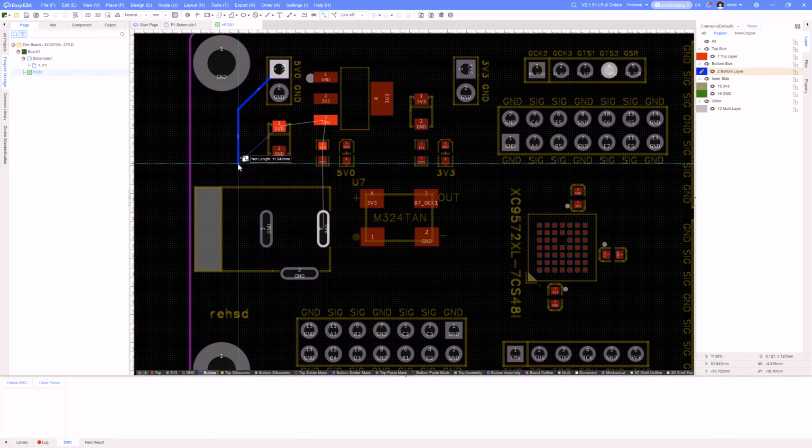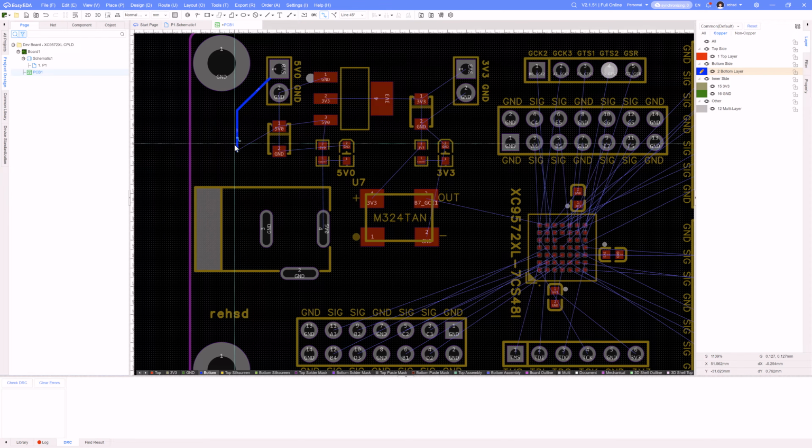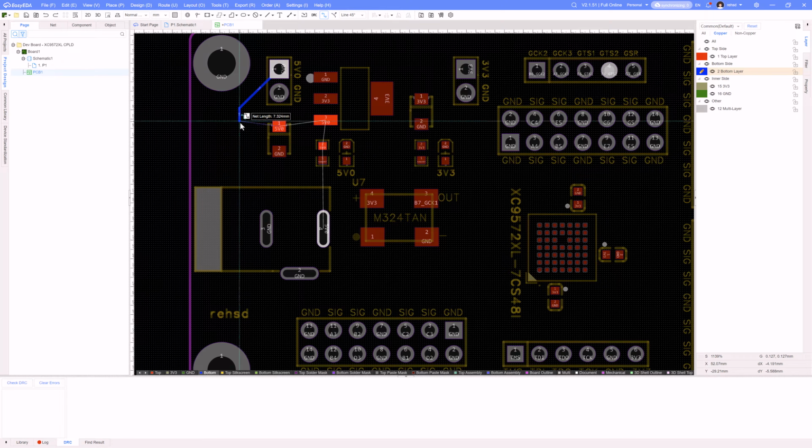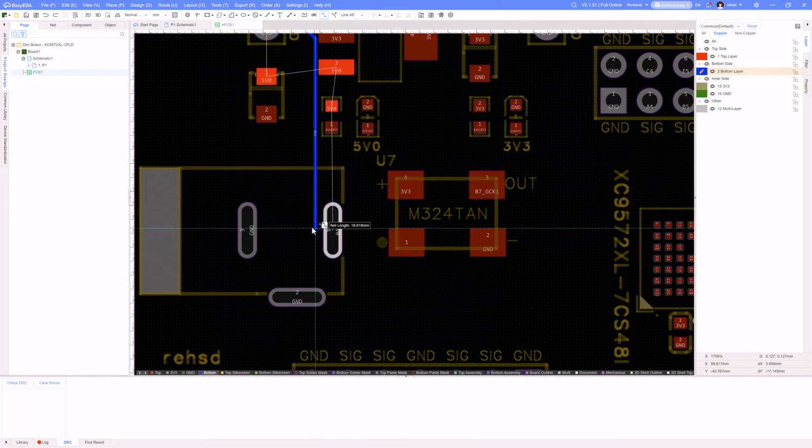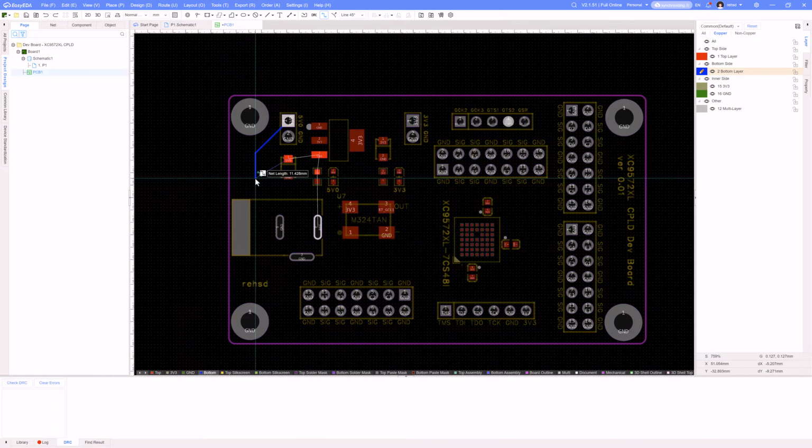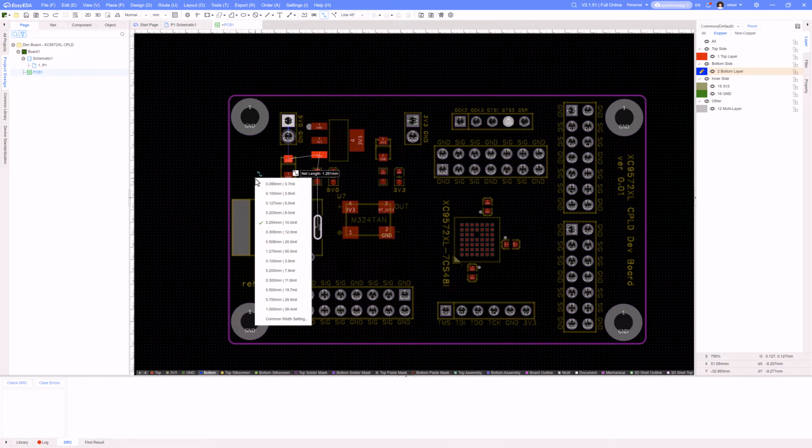Something else, I can hit Shift W. So if I escape for a second, I'll just undo that. So I do an Alt W that says start drawing a wire or a track, and then I can start working my way trying to get it down to wherever it's showing me it needs to go to. So Alt W to get into wire, Shift W to change the wire size or the track size.